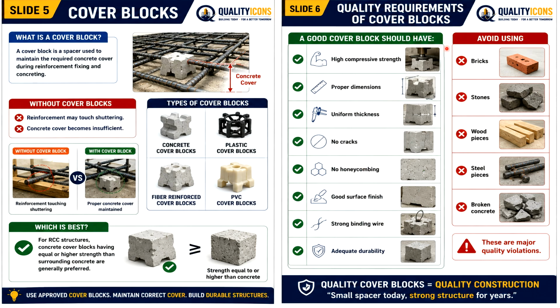Quality requirements of the cover blocks. Not every cover block available in the market is suitable. A good cover block should have higher compressive strength, proper dimensions, uniform thickness, no cracks, no honeycombing, good surface finish, strong binding wires, adequate durability.